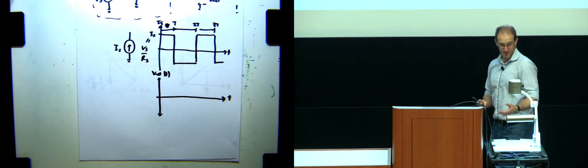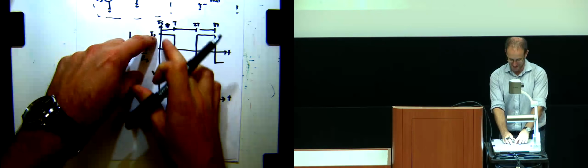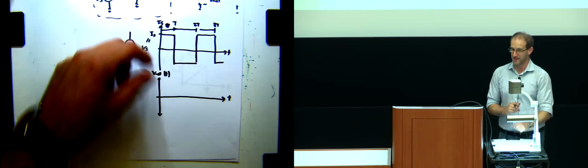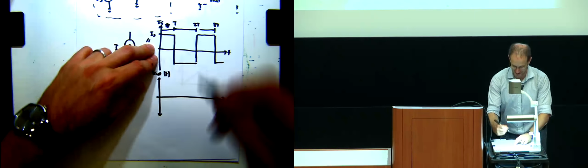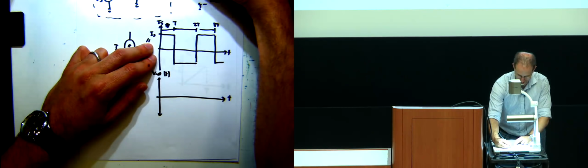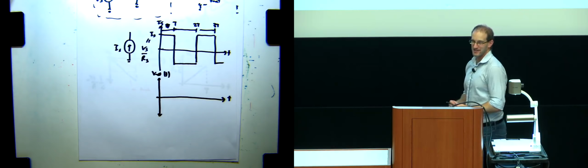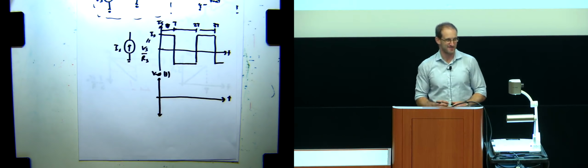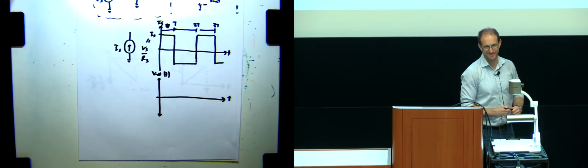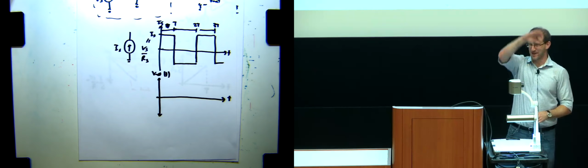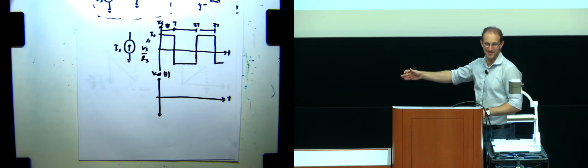Okay, so again, if this is what you go and do, you take some VS, it has this kind of square-like waveform, which would result in this IS, and let me label the IS over there. What will the V out of T actually look like? Yeah, exactly. I see somebody making this sort of hand motion. It'll look like a triangle.